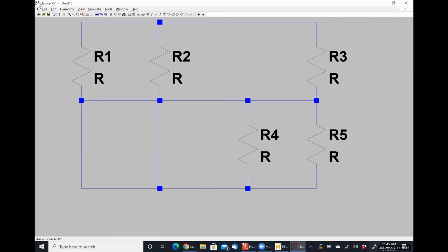I have to look at the units here because I didn't teach Circuits 1 this quarter, and so I don't remember it directly off the top of my head. Is our magnitude peak to peak, or is it from 0 to peak? The magnitude of a sine wave is measured from the horizontal axis up to its peak value. So if we were operating this guy at a frequency of 100 hertz or whatever like that, we would have 6.427 or whatever times cosine blah, blah, blah.